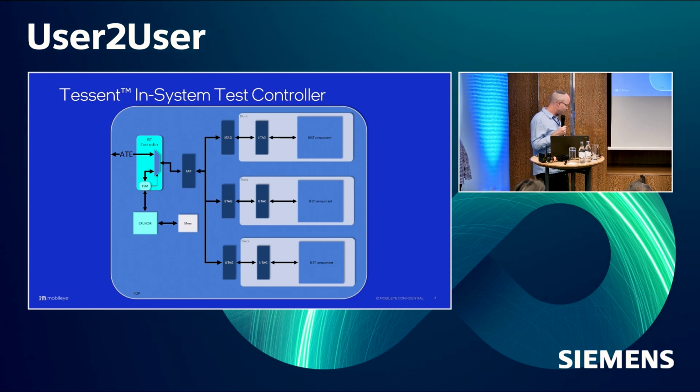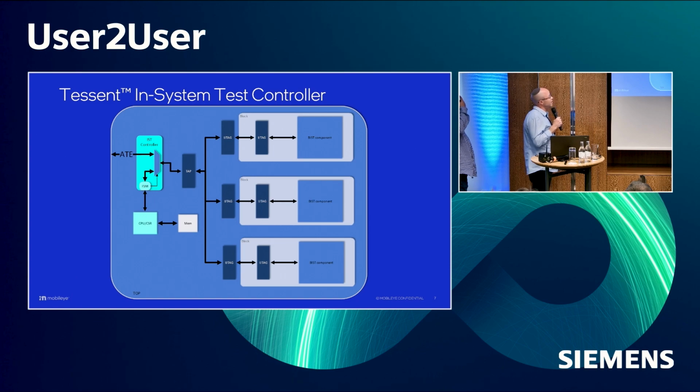In terms of the BIST component itself, eventually it's transparent whether we're in a tester environment, which is driving the test, or we're in field and we're driving the test from an internal CPU. But now if we think of it, what happens if the mission mode logic itself should have a fault?